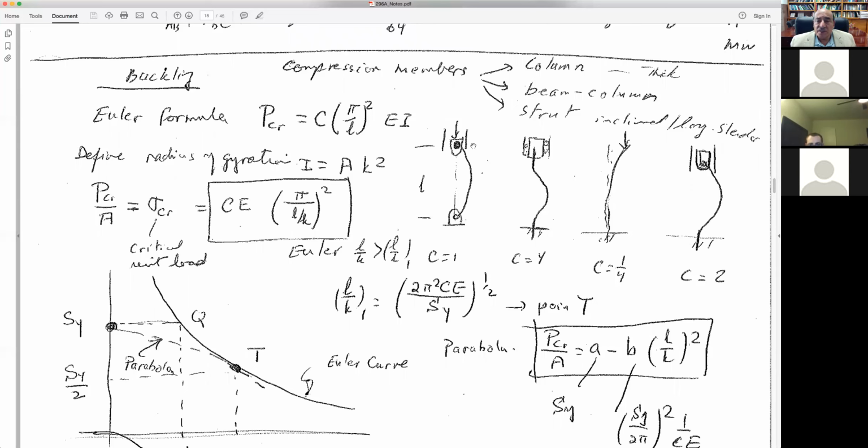These are the four different configurations: either pin-pinned, or a roller with a slope that is 0 on the rollers, or free and fixed, or pinned and fixed. These give you modes. When you solve the buckling problem, you get a mode shape like a sine curve that has a wavelength, and the wavelength adjusts itself by these boundary conditions.